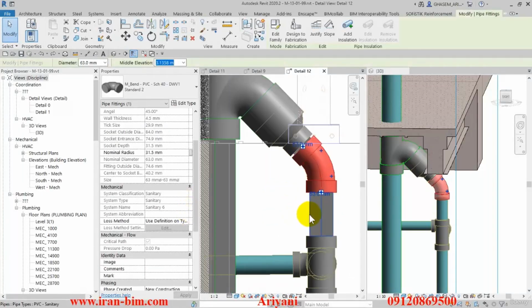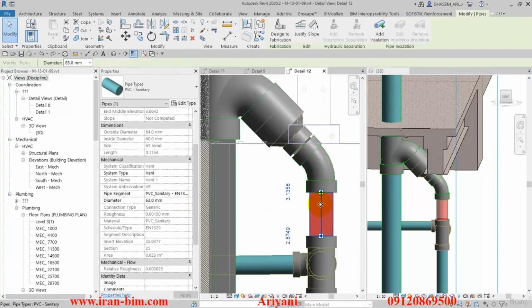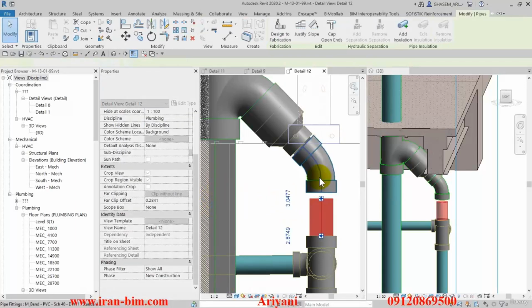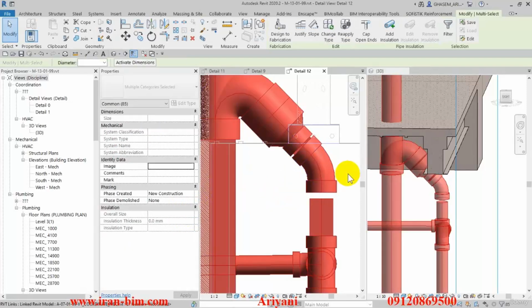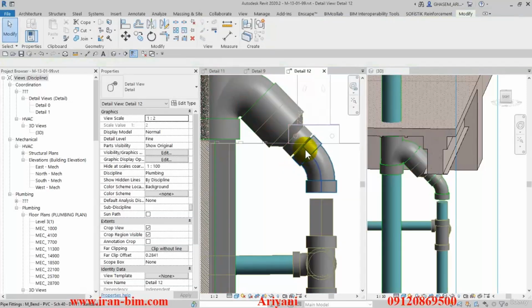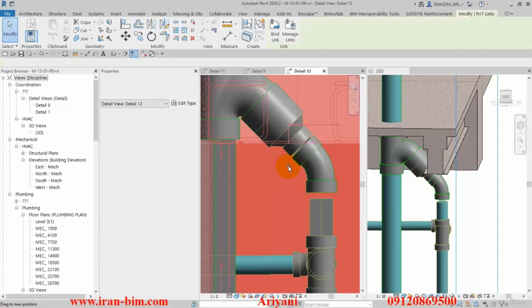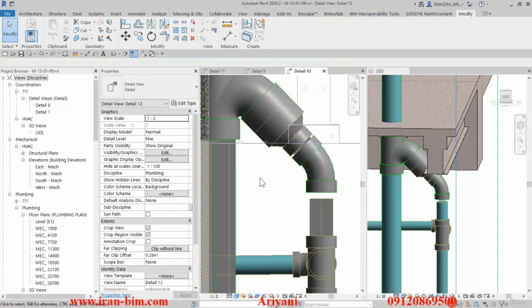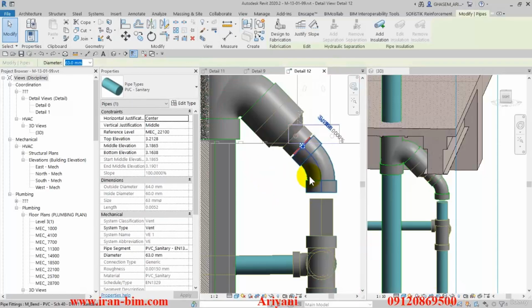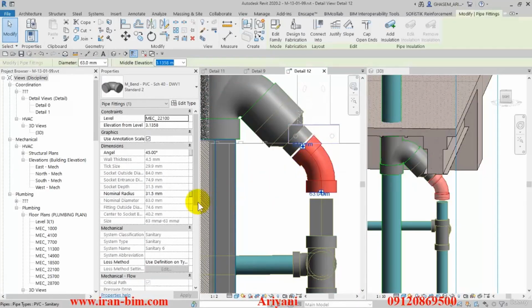Alright, then let me select this pipe over here. It's under vent, so let me just disconnect these two for a second, or I can go over here and hit tab a couple of times, cancel this, almost moved that by mistake, so then we'll hit select link, and we have a pipe here in the middle which we can delete.